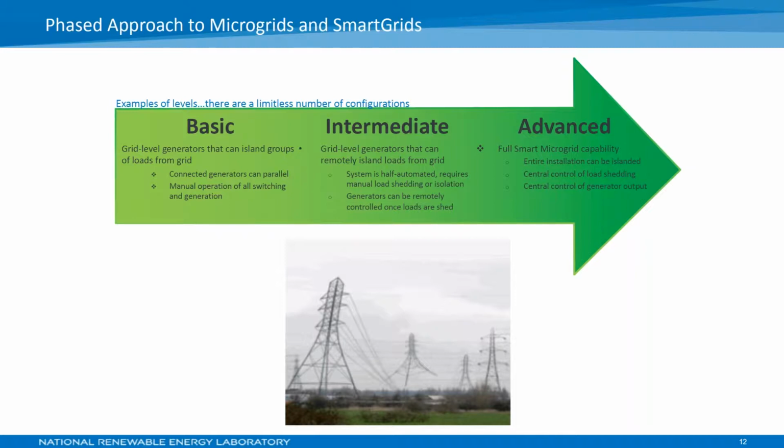So this is just trying to make the point that a microgrid can be extremely basic, manually turning on a generator and opening switches to isolate your grid, or it can be completely automated with batteries operating a system, and if there's an outage, the batteries coordinate with a central controller to open switches, and there's almost no human intervention that's even needed, or it can just check with a human to see if it's okay if we do this and move forward, is everything safe? But there's a wide variety there, whether something is manually operated or automated. Next slide, please.